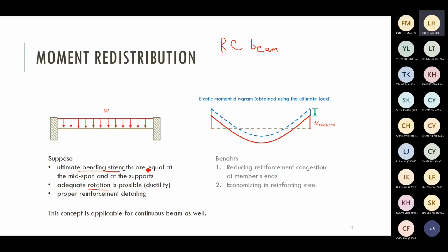Do you still remember what is local plate buckling for steel beam? Although this module is not related to design of structures, I think it's good to understand and remember this kind of basic things. Right? You have learned RC design and steel design. For steel beam, we have something called local plate buckling. The flanges or the web may buckle locally due to large axial force or large bending moment. When you do the steel design, you have to conduct section classification to classify the steel section as class 1, class 2, class 3, or class 4. Class 4 means a section with severe local plate buckling issue.